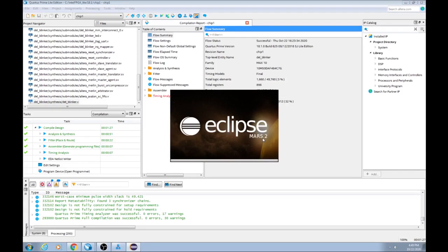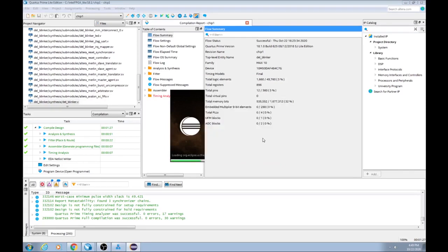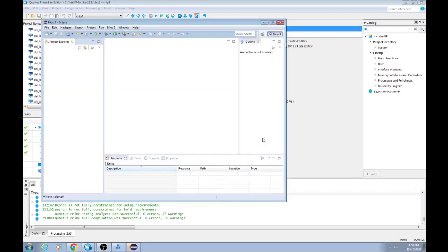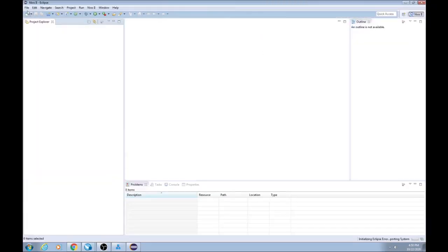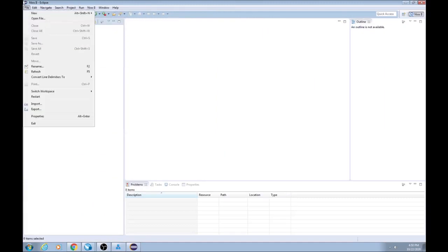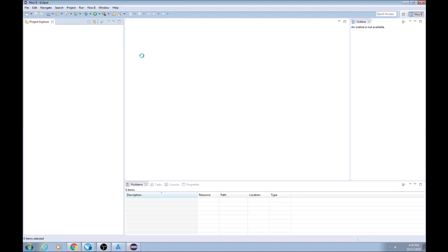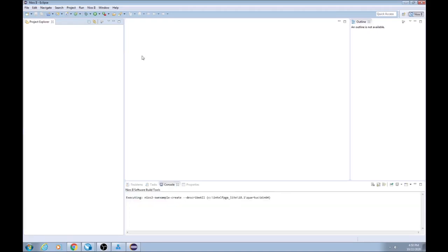So using Eclipse for C, we will assign the switch to be our input, and assign our LEDs to be the outputs. Actually program it. We already assigned the pins. We are not talking about assigning the pins. We are just activating the switches to be our inputs, and activating the LEDs,